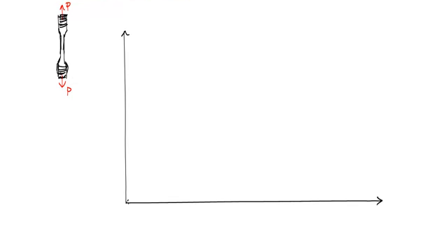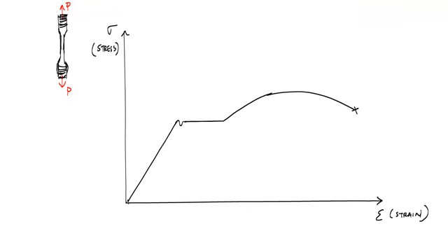And the stress strain curve for steel looks something like this. This isn't drawn to scale, but it's exaggerated so that we can identify different regions, and I can write them down here all in one drawing. When we do a stress strain test for a steel specimen, what we have is this first portion right here, from zero load to some increasing load. We have what is called the linear elastic region, which is a straight line, right?